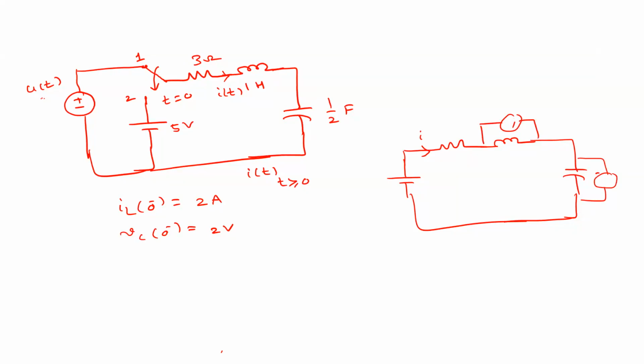Here in the question, you are asked to calculate the current, right? If you represent with voltage sources, for example a voltage source here and another voltage source here, the advantage is that straight away you can apply KVL, right? So if you can apply KVL, you can get the voltages. Understand? So what we observed is that instead of using a current source, if you use a voltage source, the problem will be simplified.